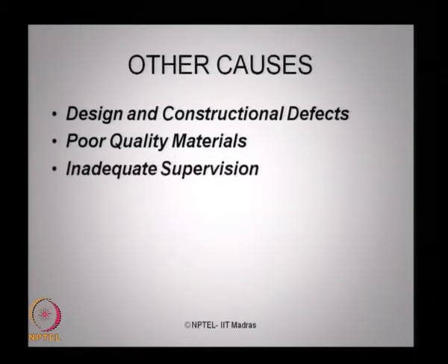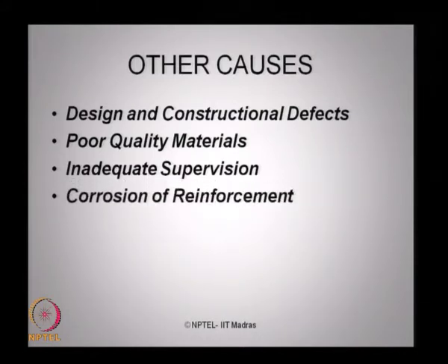Above all, a very important factor which people have now started paying more attention to in terms of concrete structures in sea environment is inadequate supervision. When the supervision is not properly and technically carried out for the construction of offshore and coastal structures, ladies and gentlemen, we must agree that this also leads to one of the important factors which degrades the function of concrete in marine environment. So, concrete as a material cannot be blamed alone for its strength degradation. There are many other factors, for example design fault, construction defects, poor quality material, inadequate supervision, and there can be corrosion of reinforcement as well. Therefore, these are all added causes which add to strength degradation of concrete, especially in marine environment.